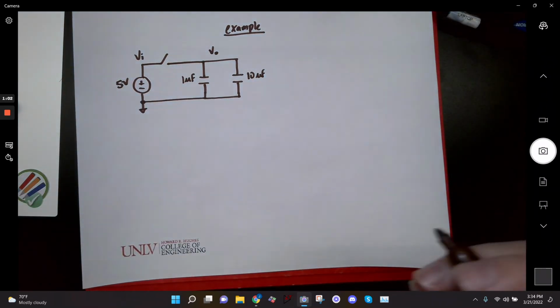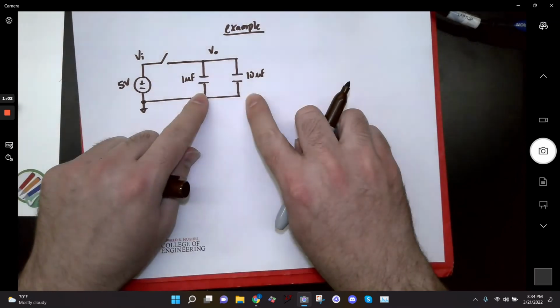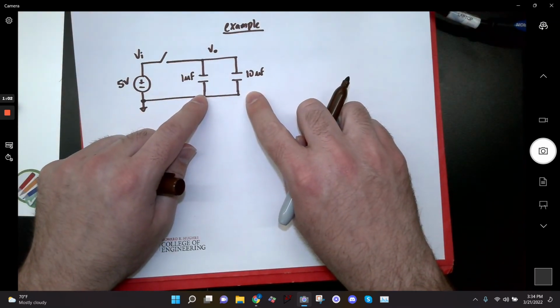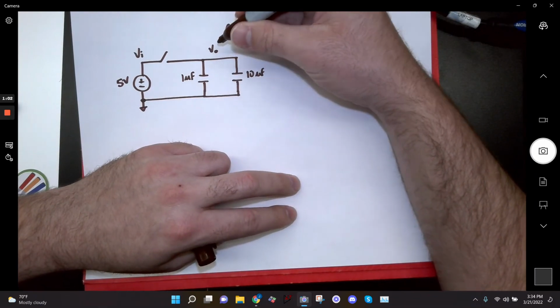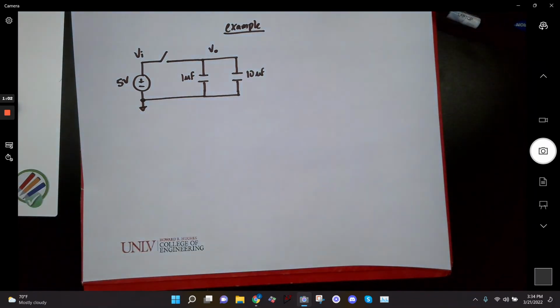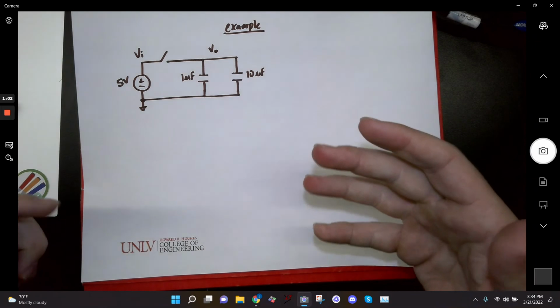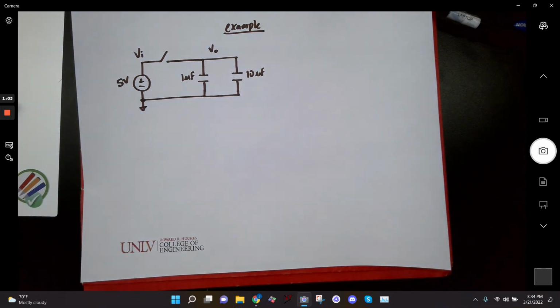So if I want to make sure that Spice knows I want these capacitors initially discharged, I can write a statement in Spice to set V out initially to 0, right? But there's also going to be times when I want them to be initially charged because we're going to work on discharging capacitors also. So you will go into Spice and set them to be initially charged.